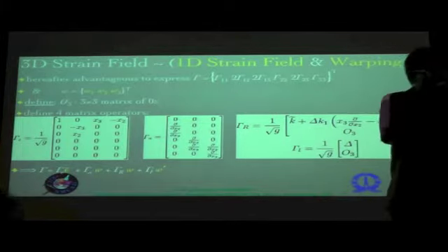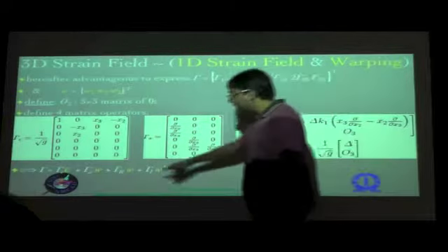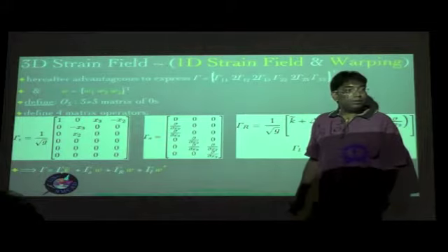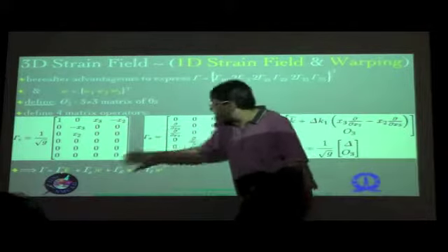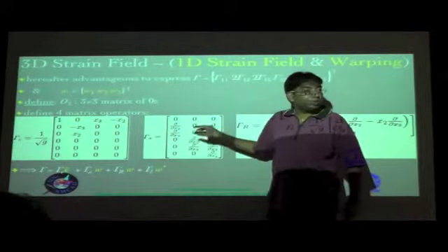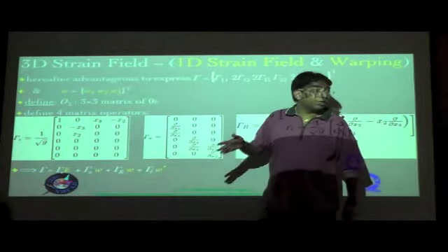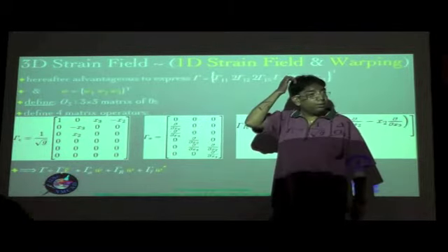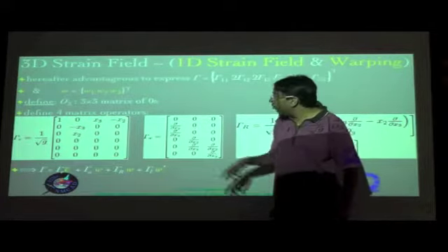Yes, please. So delta A as a Gamma A has a contribution from bending other than this pre-twist and pre-bending. Whatever bending takes place, right, sir? No, gamma A is not dependent upon initial twist and curvature. It's purely dependent on the derivatives of the warping with respect to the cross-sectional coordinates, with respect to x2 and x3. In-plane warping contributions. Also, it involves W1 as well.